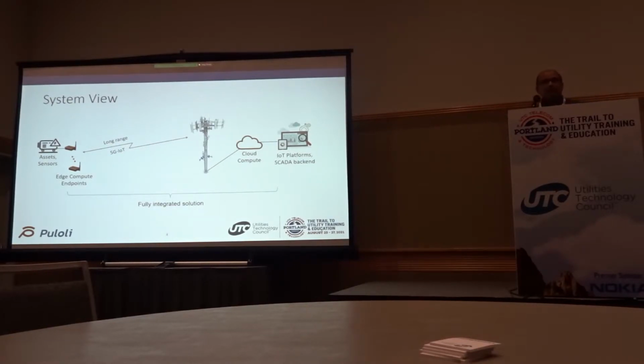So typically, in the cloud compute will be the interface that talks to the legacy systems using the existing protocols and handshake. Whether it's Modbus TCP or any of the legacy interfaces that SCADA platforms or IoT platforms use, they will be talking the same language, existing protocols. So the idea is that you have minimal impact on the backend, and you fully modernize and upgrade your front end.